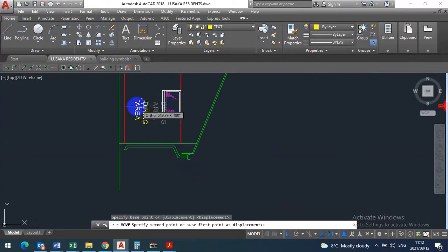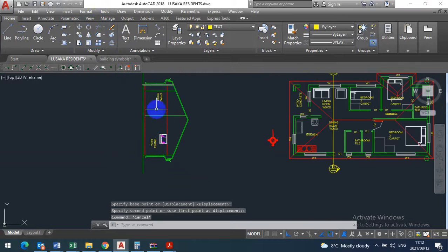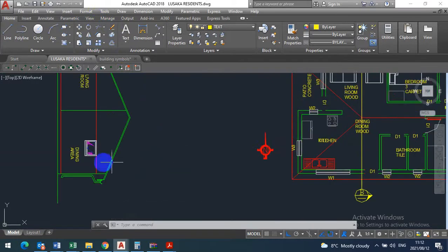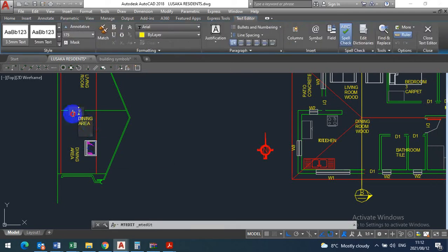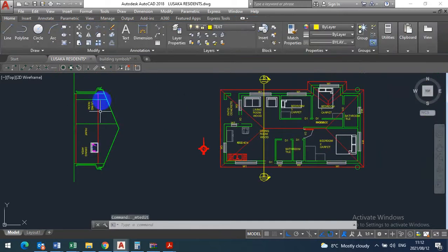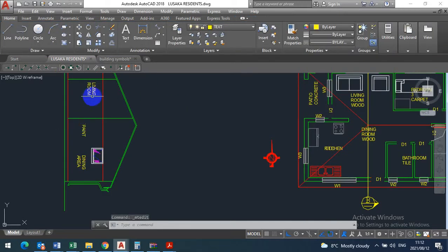You're going to move the name. We need the names. And the finish. What's the finish? What's the wall finish here? If it's paint, you are going to just copy this to there. Double click. You can say paint or face brick, if for instance it's face brick. Okay, so if it's paint, you just say paint, enter. Then we know the entire wall is paint. Okay, everywhere. This is just the name of the room. You can move it nicely in position.